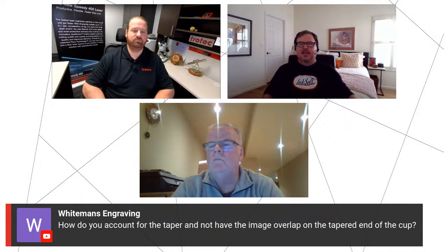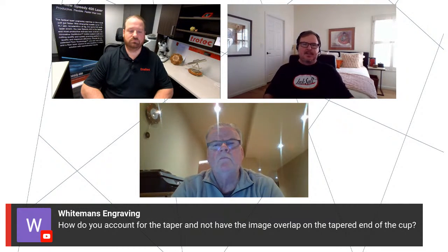One piece of advice I would give too, when I do the business side of my training, is just because you can doesn't mean you should. You have to design things that are production friendly, that will reduce the amount of spoilage you have. Trying to do that taper thing, you are going to increase your spoilage, but there's certain things you can do in the designs.